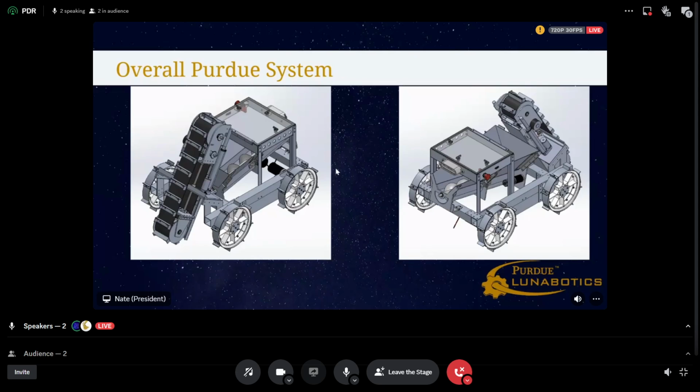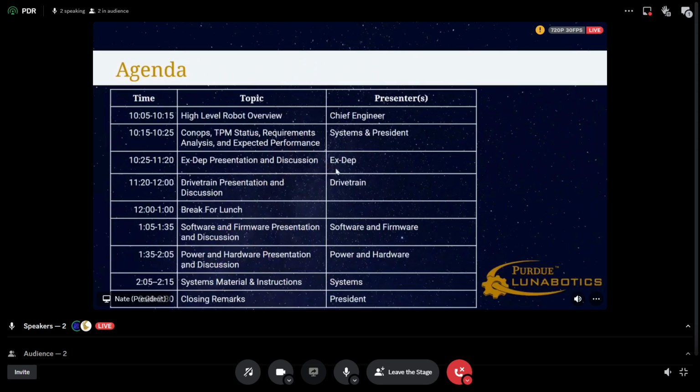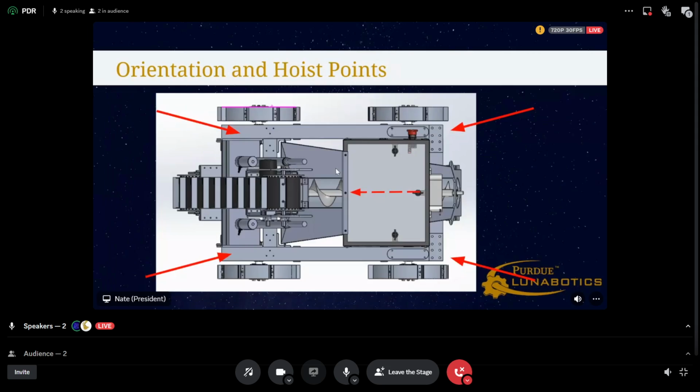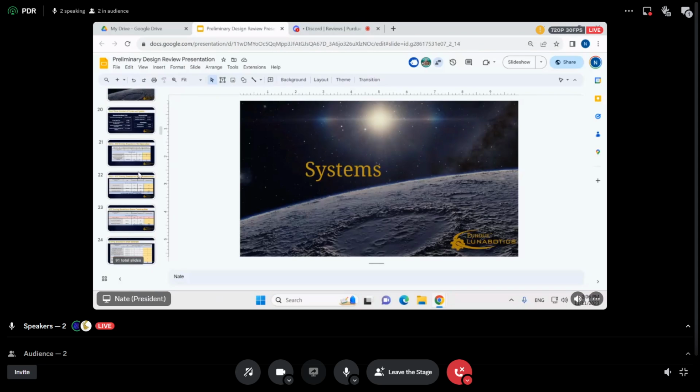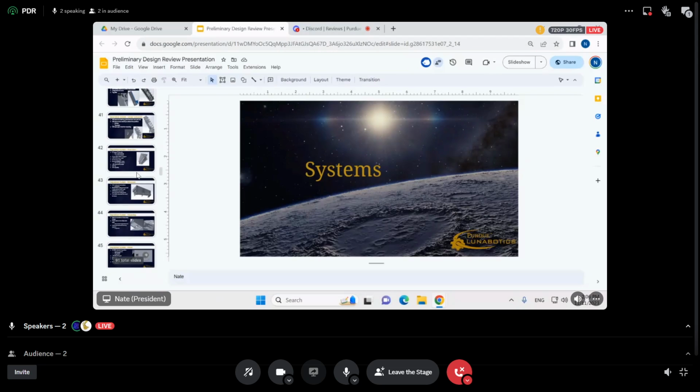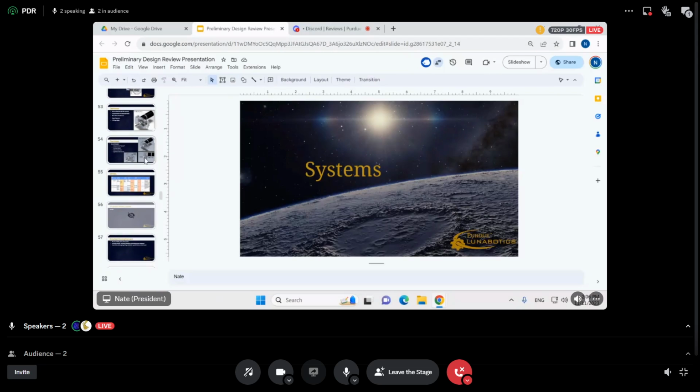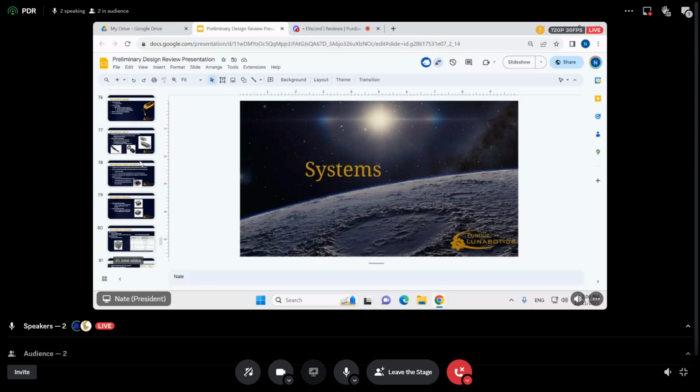Question on the breakers. For the drivetrain system, if one motor is stalling, the breakers would not trip, right? So we sized it for one motor stalling. Because if both motors are stalling, it just means the breaker trips even faster.